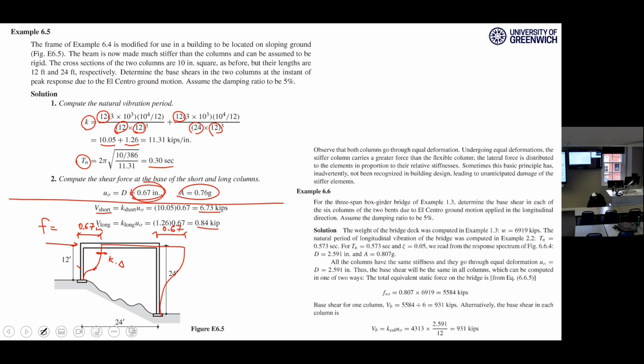Yeah, this point is going to focus on the fact that the forces from an earthquake are not going to be proportionally distributed to all columns without any difference. So if you have different columns with different height, the internal forces can be very different based on this fact. And that's the point.